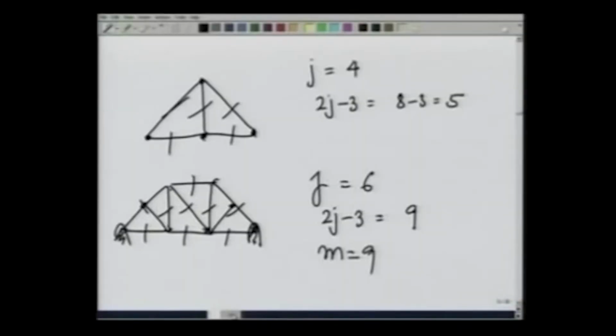In the previous lecture, you noticed that both the ends are put on a fixed point. Actually, this makes the system indeterminate because the number of external forces is now 4. We could make it determinate by putting the right hand side of the system on a wheel or on a roller. Let us take one example of this.